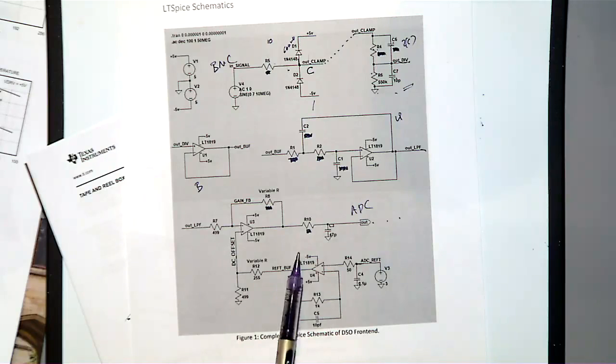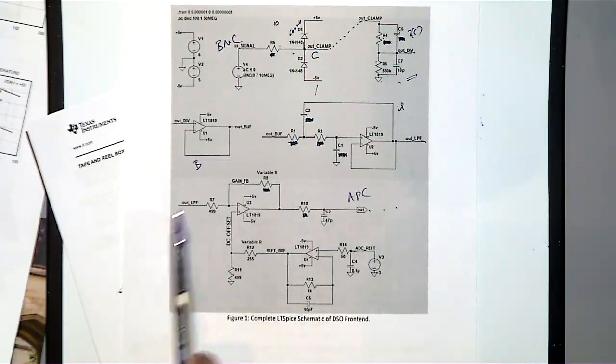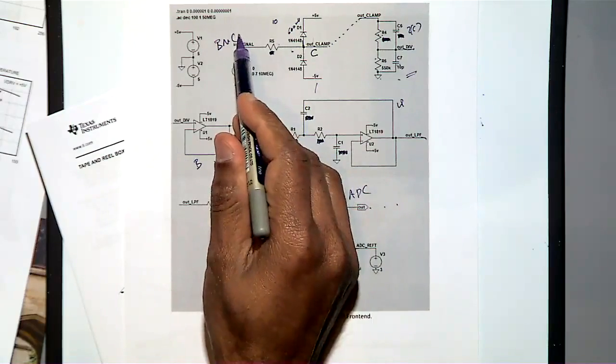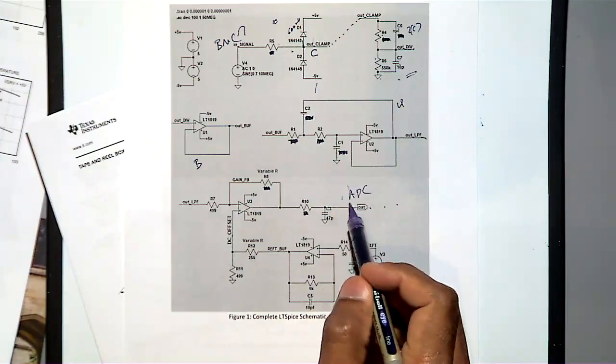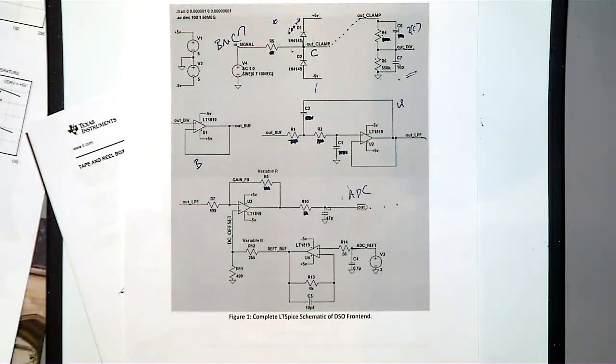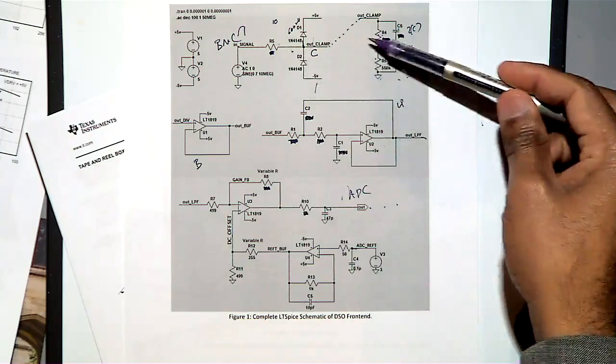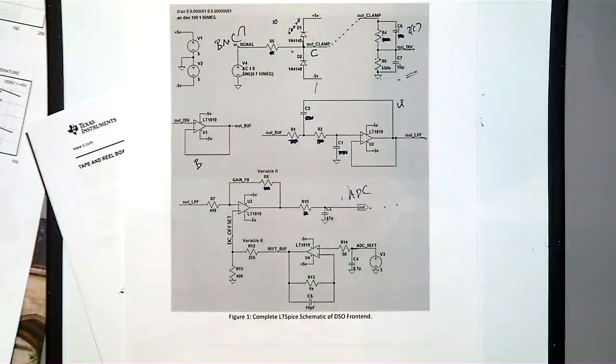And then here also you should be writing something about this block. This is a level shifter and amplifier, and then you should be thinking. Another thing you have to do is your signal. If the signal is something like this, at the end again it should be the same. If it is inverted, you need to add one more inverting stage in between. So you have to make sure of that design. But in this example there is no inversion, you can check it. So you have to write about each block, and then why the value is selected.